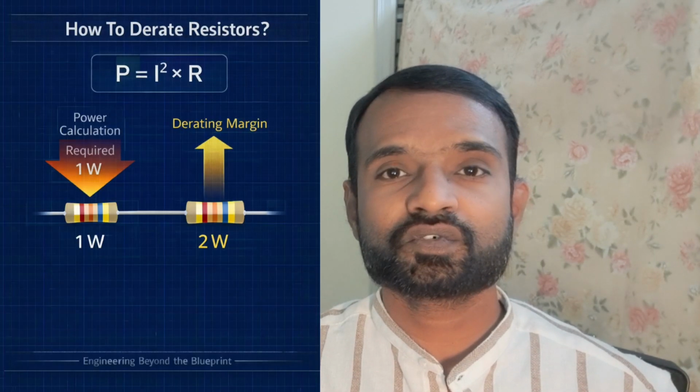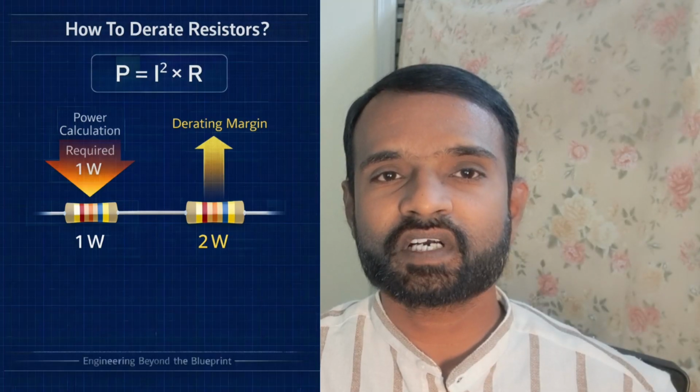Now getting to the middle level engineers, who fall under 2 to 5 years of experience, the questions would be something like this. Resistor selection for power circuit. Yes, of course. Check resistance and power rating, temperature rise and derating. Example, if calculated dissipation equals 1 watt, the rating should always be greater than or equal to 2 watt